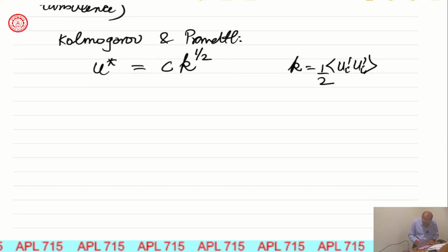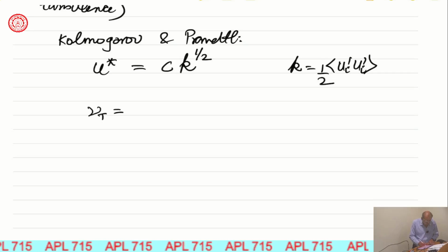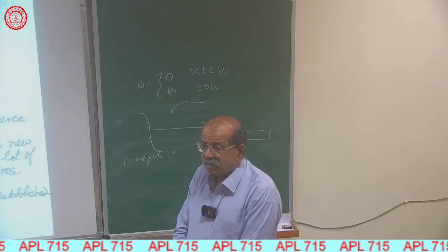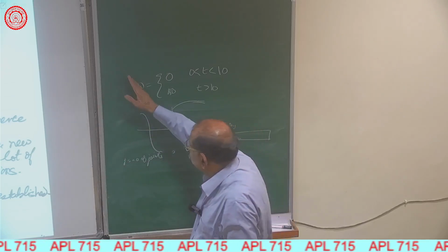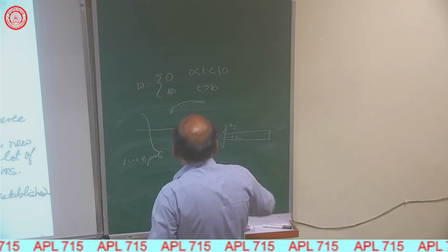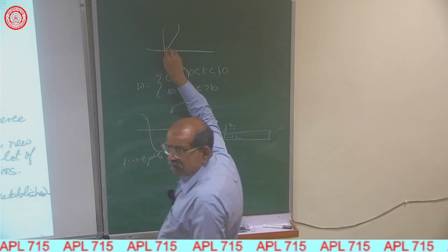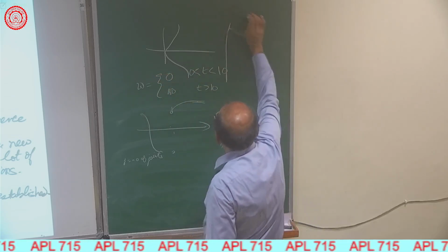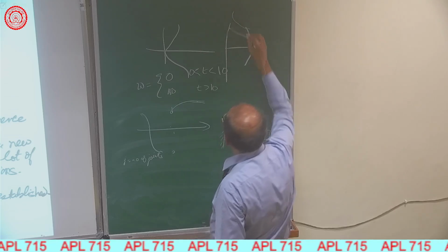Why is it a problem to have a Reynolds stress of 0 at y equal to 0? Because Reynolds stresses will also go to 0 then. But when you solve it, your Reynolds stress profile will be a continuous profile, whereas actually you know the Reynolds stresses are almost constant, and they go to 0 only at the edge of the boundary.